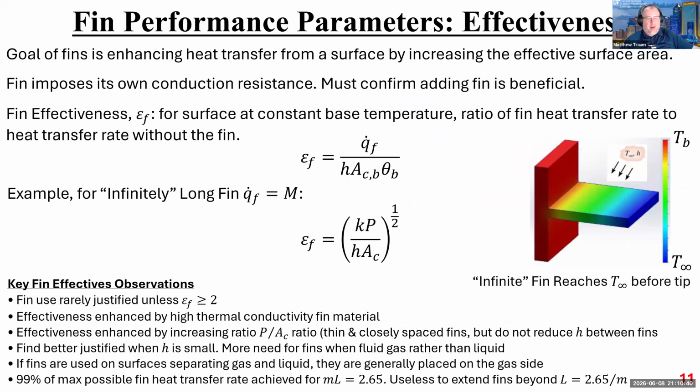So it is important to come up with some performance parameters to know that what you've designed, or to guide your design process so that your fin is helping and not hurting. So I say here, fins impose their own conduction resistance. You must confirm that adding a fin is beneficial before you add it, right? So this is an important step.